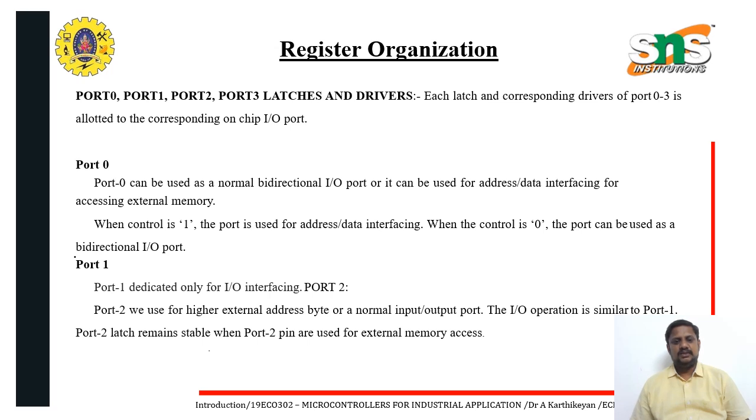Also, when the control is 1, the port is used for addressing and data interfacing. In case the control is 0, the port can be used as a bidirectional IO port. So based on the zeros and ones it will vary. If it is 0, it can be used as the bidirectional IO port. If it is 1, we mainly use it for addressing and data interfacing. That is port 0 operation.